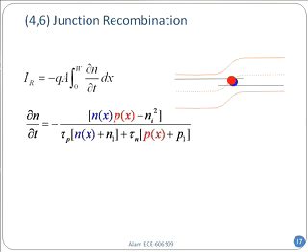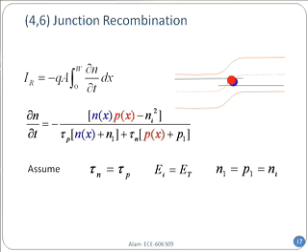This is a complicated expression. What expression is this? This is the Shockley-Read-Hall expression. But this time I have written it as a function of n(x) and p(x), because carrier concentrations are not constant everywhere. You have solved this problem in your homework. Now let's try to calculate this n(x) and p(x), and we'll insert them in and see what happens.